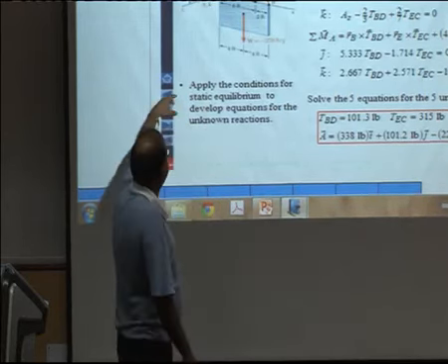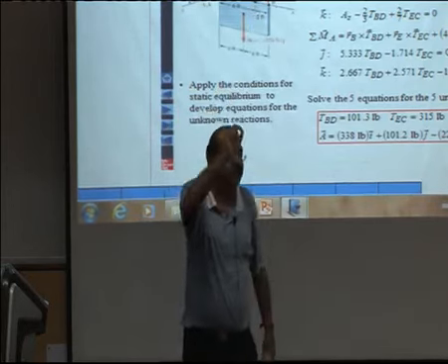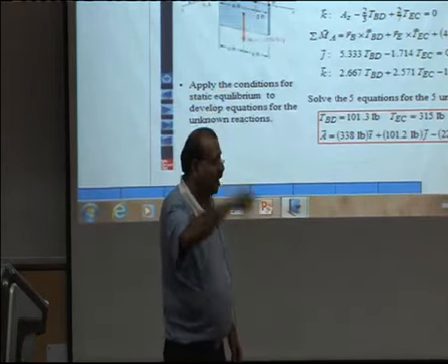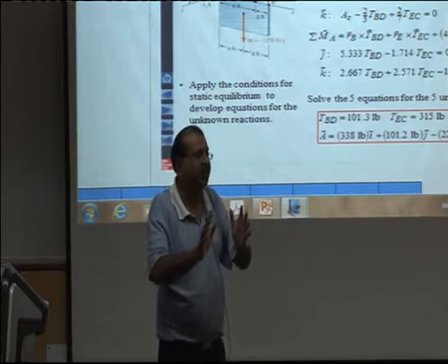And for the vector equation, the best thing would be wherever these forces are acting, you call the position vectors r1, r2, r3, and the forces f1, f2, f3, and then don't try to physically work out the moment.